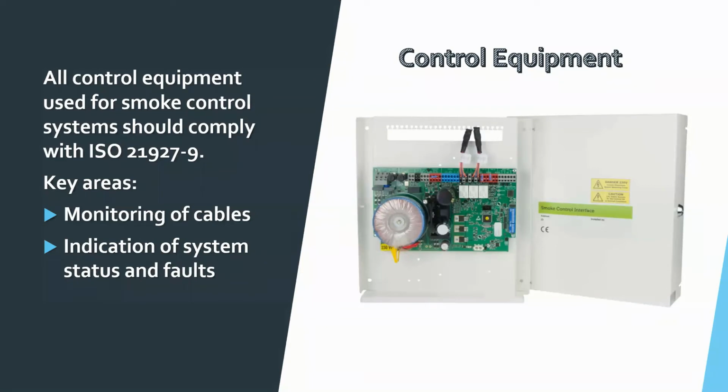Control equipment is now part of today's technical requirements supporting the building management system. Controls play a major part, often linked to the BMS and fire alarm system. It is important as it can identify for the fire teams where the fire is located, the condition of the equipment and what elements are operating. These controls should be regularly inspected to ensure they are performing and monitoring as originally designed and still fit for purpose, which also covers the cables and the system status.